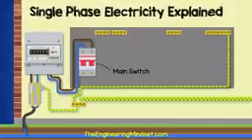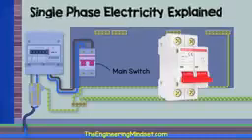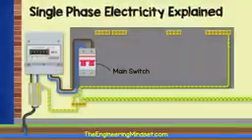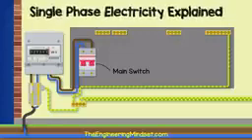This controls the supply of electricity to the rest of the consumer unit and therefore all the circuits feeding the property. This switch is not automatic and must be manually flipped to cut the power. This switch will disconnect both the phase and the neutral line together. The cables typically enter the main switch via the top terminals.